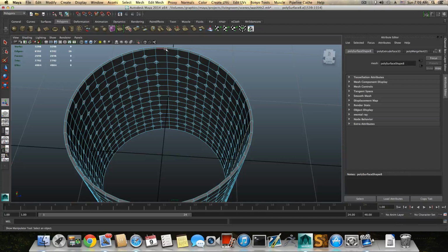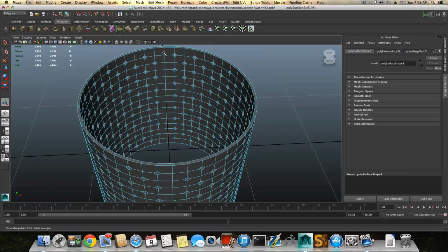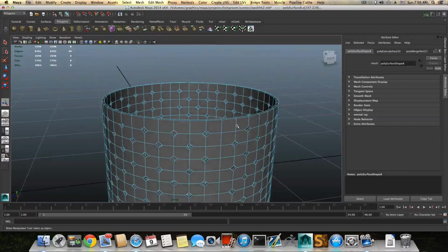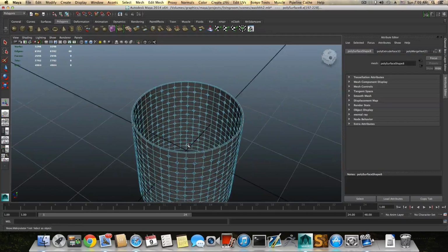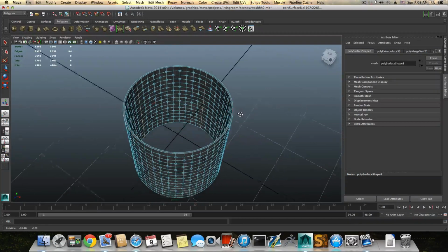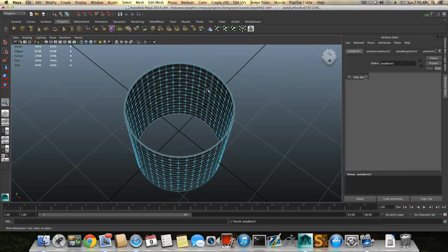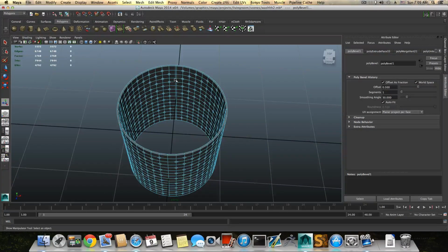And we are going to do this also for this one. Shift select this one, shift double click this one, shift this one, shift double click this one, so it's not selecting anything outside, only inside there. Okay, shift select this, double click on this one, and now hold the shift, right click and choose Bevel Edge, so it will bevel this that way.